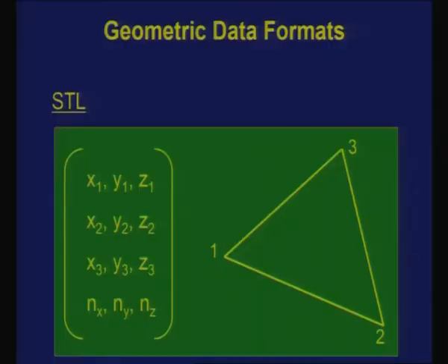And apart from the triangle information, when you open an STL file, what you see is an object which consists of, let us say, about 3000 triangles. I have XYZ coordinates of all the triangles. It not only stores the 3 vertices' XYZ values, it also stores the normal information. Whenever I have a triangle, it has 2 normals. I have XYZ, but I also have NX, NY, NZ.